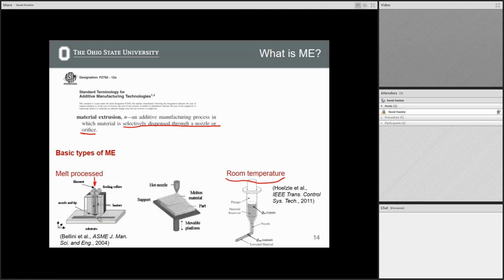It comes out the nozzle, so it's basically going solid to liquid here. And then when it extrudes out the nozzle, the heat source around it goes away, and it has ambient temperature on it, so it solidifies again. So you're making things by a phase transformation, just like powder bed fusion. In the other methods, you're basically going from solid, liquid, solid, right?